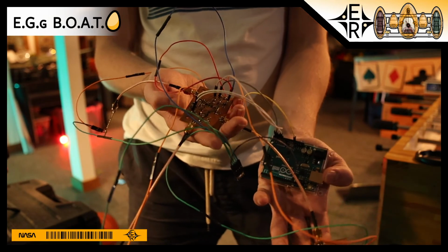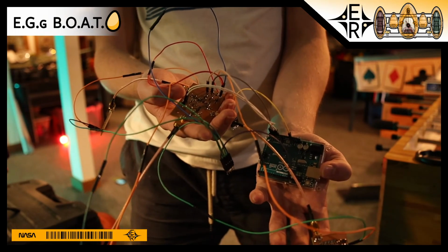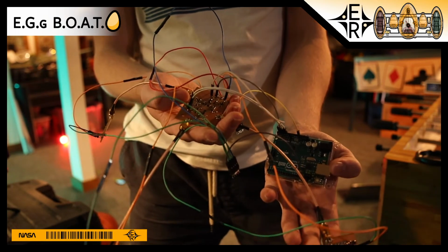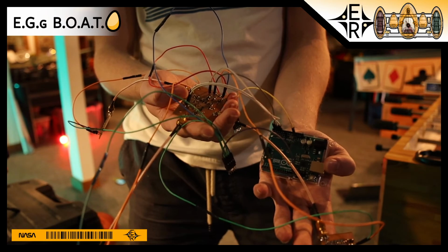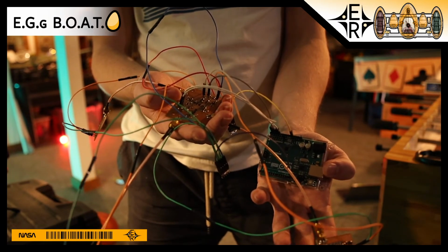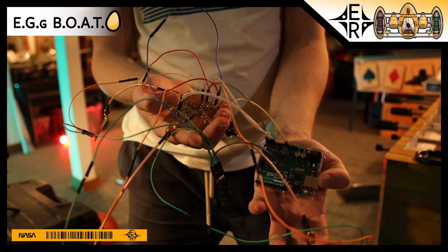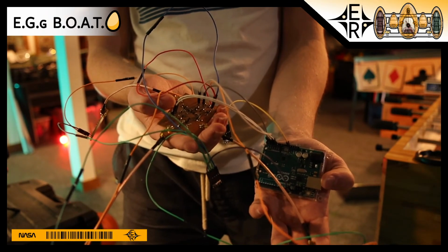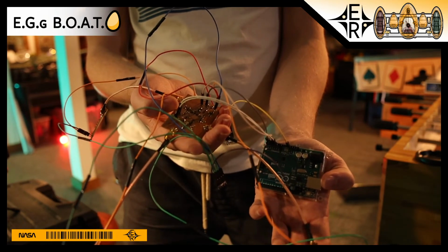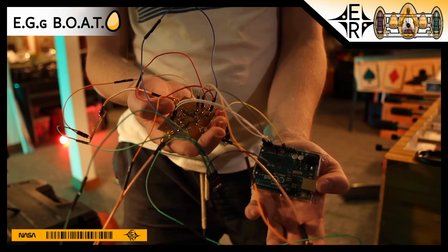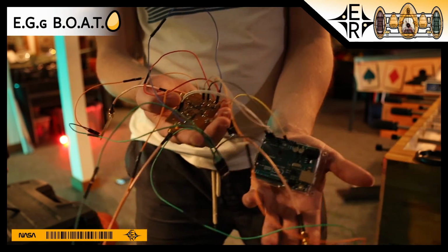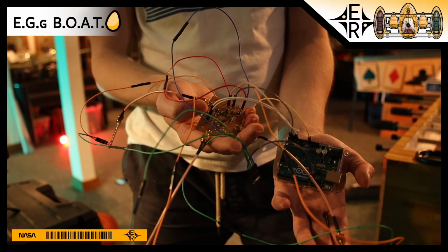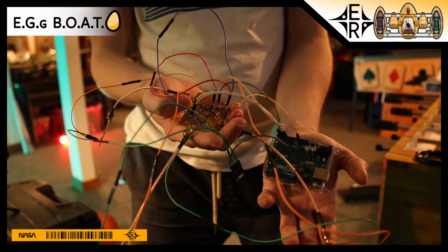All those square waves will go into the high speed phase comparators to compare both antennas 2 and 3 to our reference antenna 1, and those will output square waves with varying duty cycles depending on what the phase difference is. Those square waves will go to an AC to DC converter, which will take the average value, which we will read with the Arduino, and from that we can infer and calculate what the angle differences are.